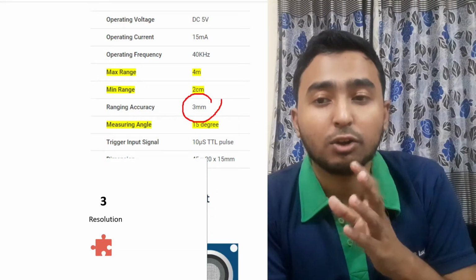Next up, we need to think about the resolution it gives us. It is the smallest increment detected by the sensor. In the previous example, the resolution was around 0.3 centimeter, so that's the unit it calculates progression in, and it can be one of the most crucial factors, if not the most, in deciding how precise your data is. Fourthly, we need to consider the model fit.